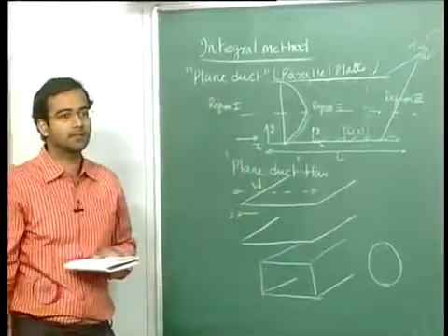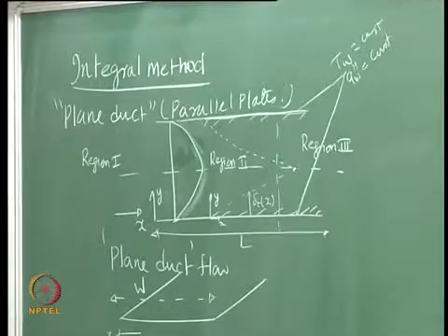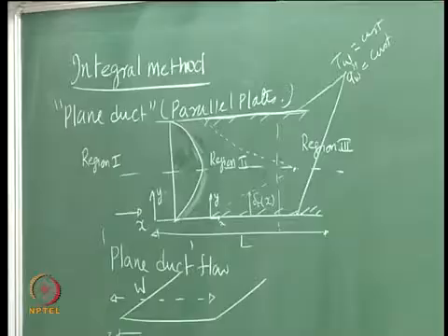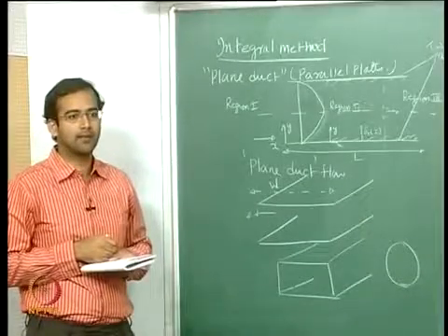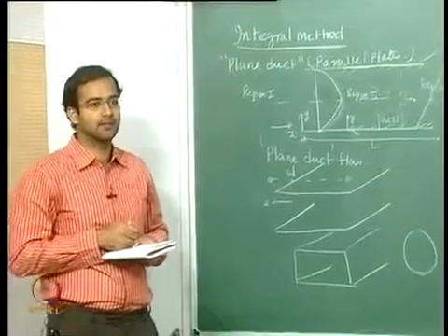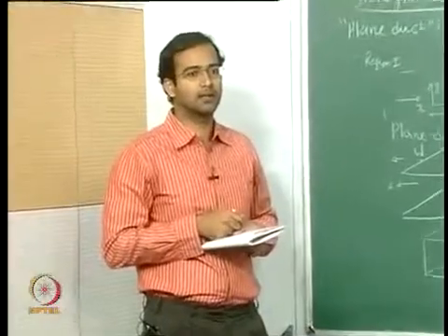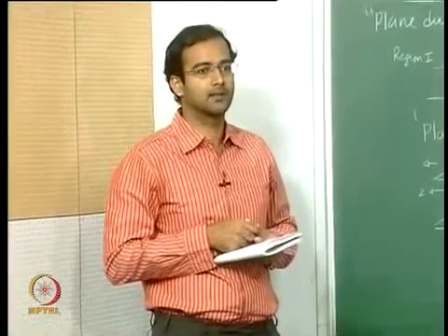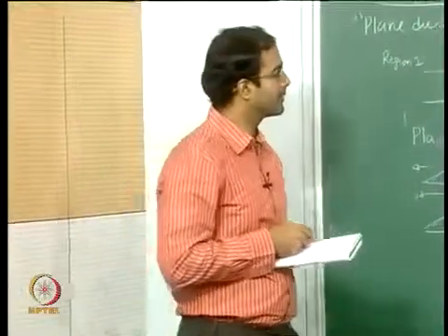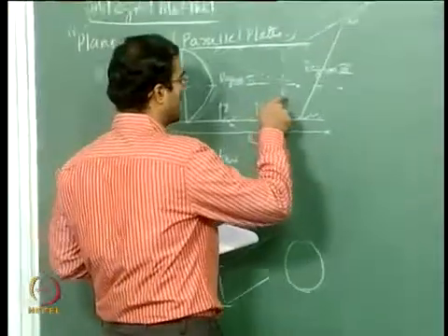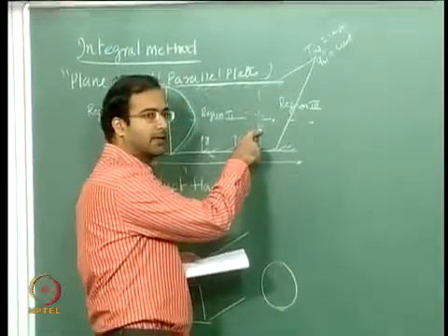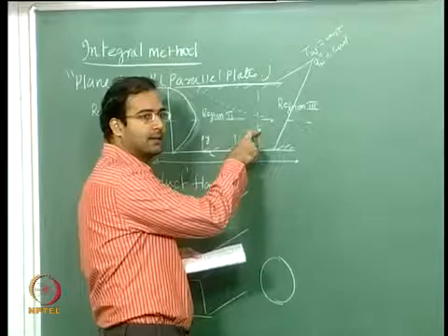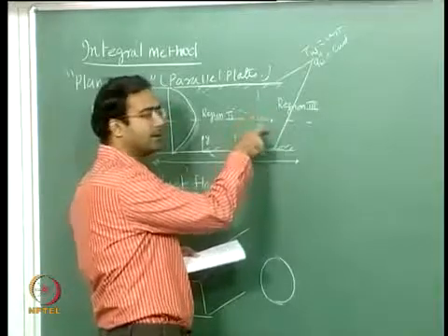The two boundary layers growing from the top and the bottom walls come close and then finally they are about to merge. In such a case, your boundary layer approximation will not be accurate. Okay, so you cannot therefore apply your momentum integral or your energy integral approximations in this region,